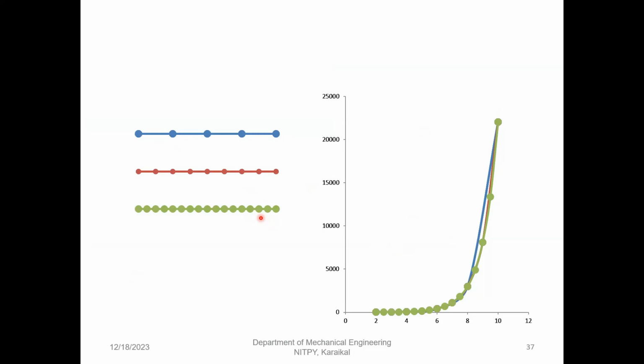But in reality, if you have a 7-point mesh, you'll be getting the same results, but by a faster method. So this is the advantage of grid refinement. Wherever there's going to be gradient, I'm putting more cells, and where there is not much gradient, I'm going to go with the coarser mesh itself.